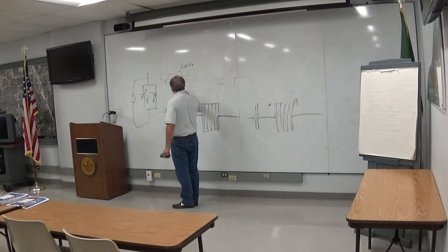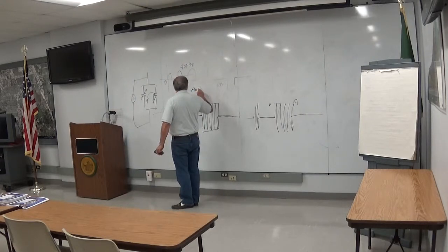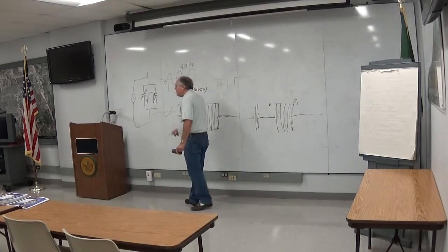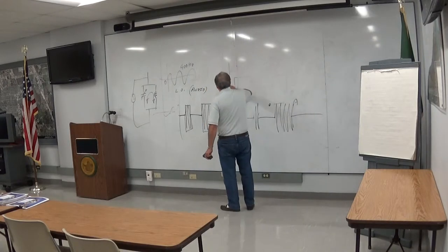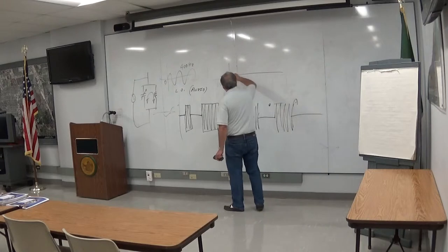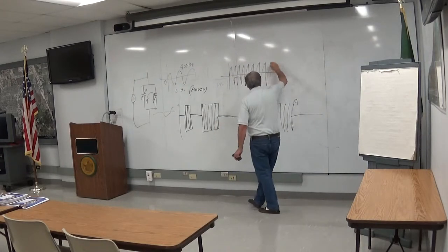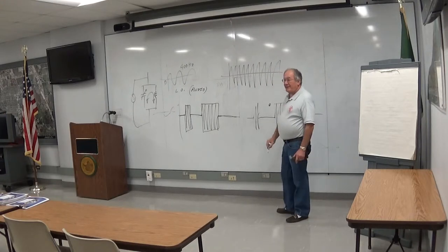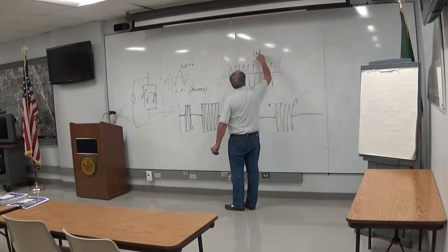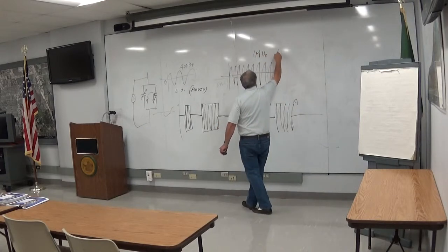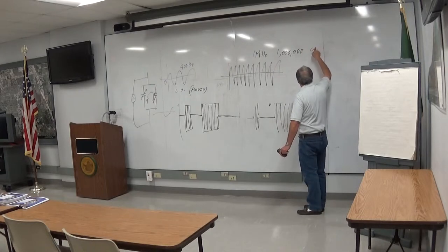All right, that's the local oscillator. The low frequency component, the audio. That's your voice. That's the part you want to put on the air. What about the thing that is the air itself, the radio frequency? Well, sort of like I described with the Morse code. It's going to be oscillating many times that rate. So I said 400 hertz here. Let's just say it's 1 megahertz here. 1 million cycles per second.